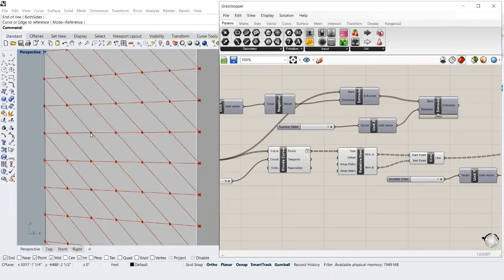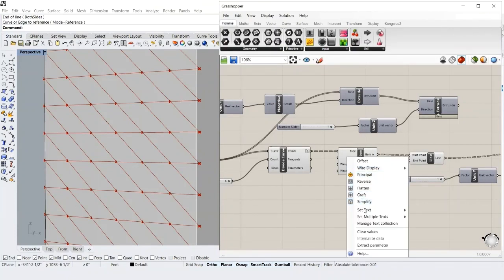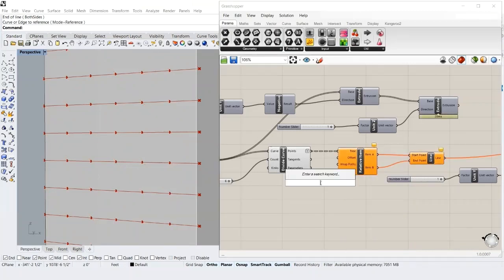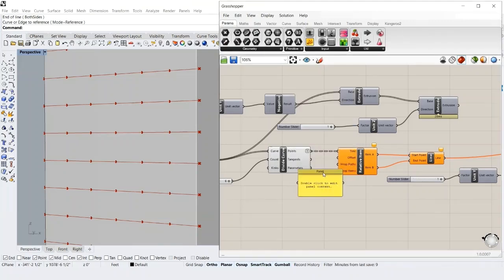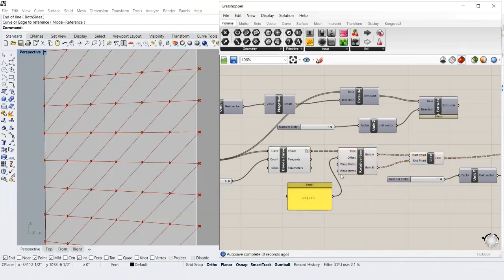There is another way to set up the offset. In the side text, click the green button. Double-click on the canvas. Type panel. Enter. Double-click on the panel. Type the code. Click on the canvas and plug it into the offset. Click the update here.